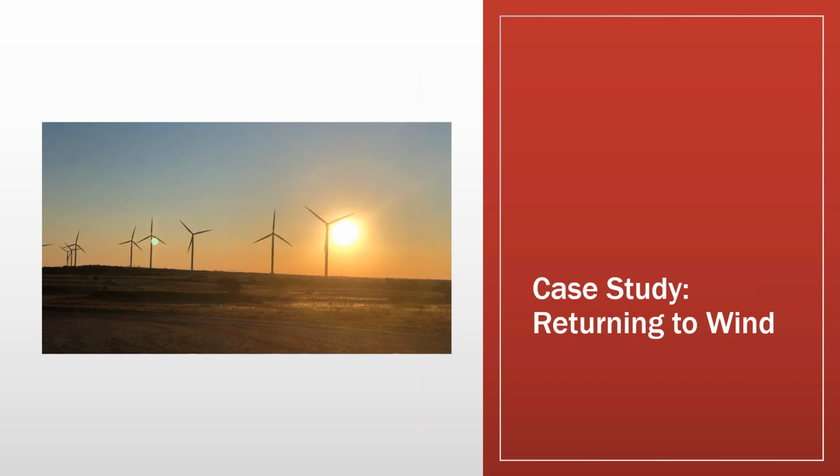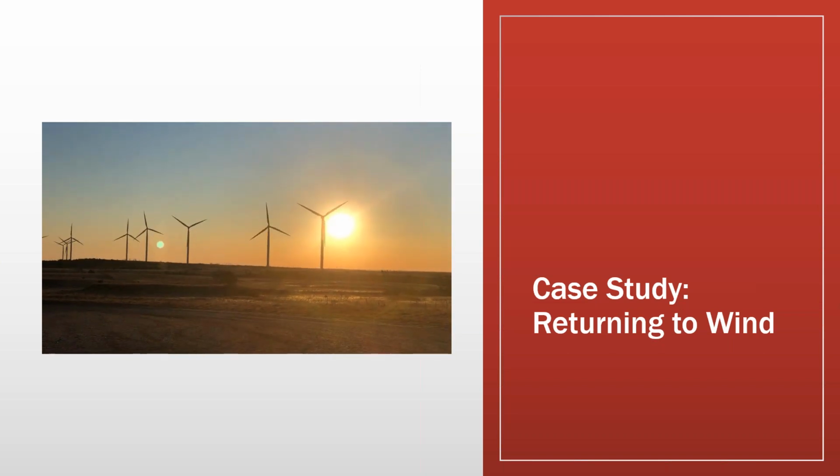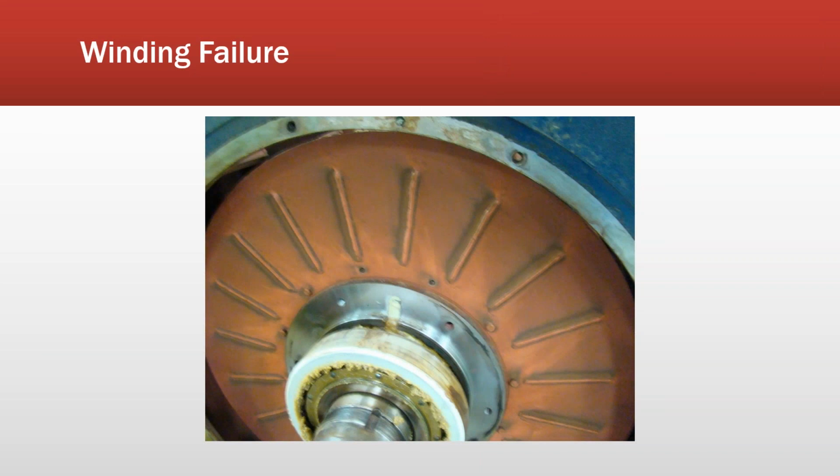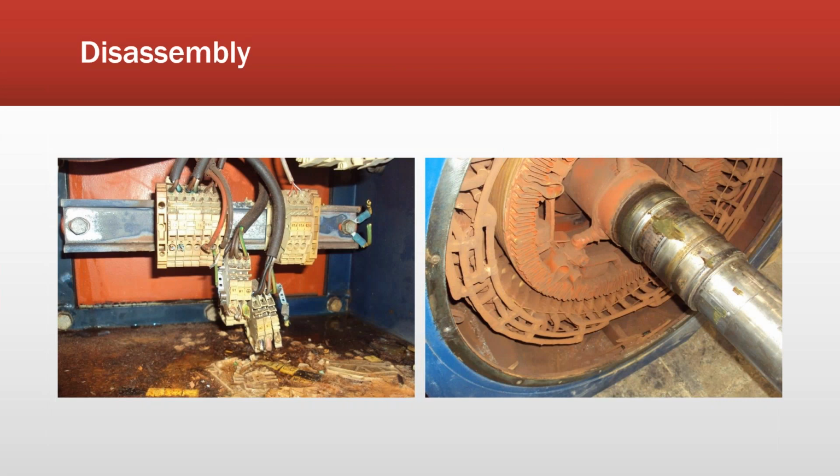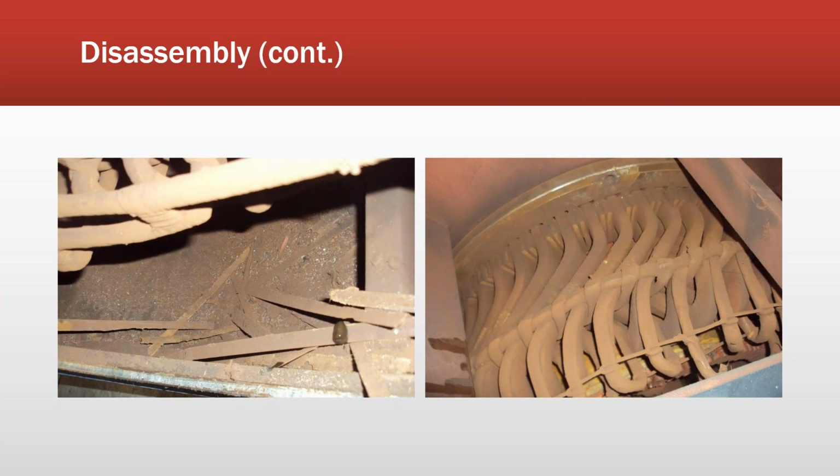So let's take a quick look at wind. This goes back to the wiring failure. This was 2010. We did an RCFA. It was pretty advanced, looking at the reason for missing wedges. This was a cold weather machine, northern Minnesota. Basically, one of the discoveries we had was the plastics being used were not able to manage the minus 40 degrees centigrade that they saw on occasion. All this brown, by the way, is magnetic dust from the wedges.